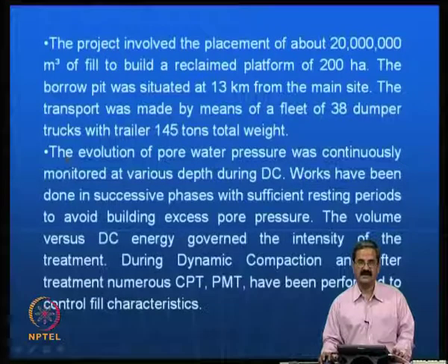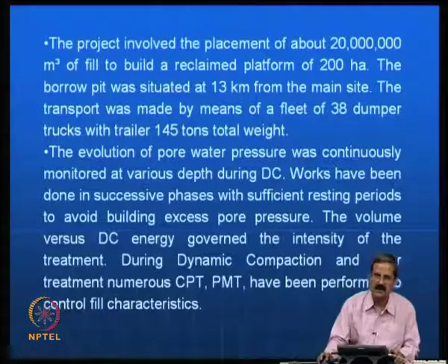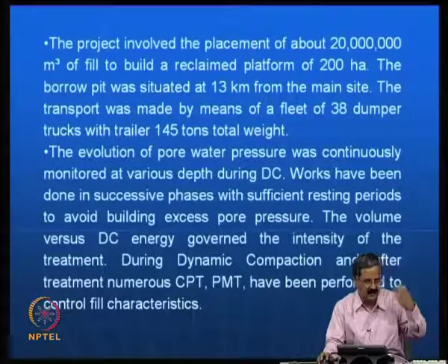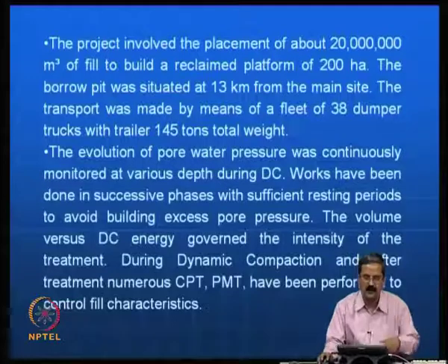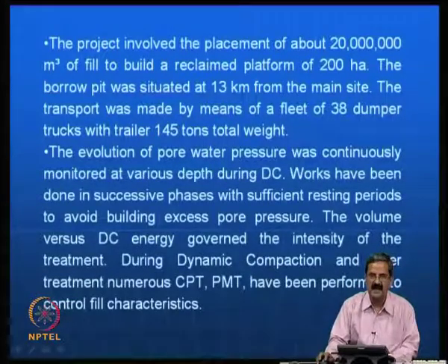So in this case, the pore pressure was continuously monitored at various depths during the dynamic compaction. As I just mentioned, the pore pressure variations during dynamic compaction have a very significant role in deciding about the construction, the tamping operations, the release of load and all that. So the work in this case was done in phases with sufficient resting periods to avoid building up of excess pore pressure. The volume versus DC, or the dynamic compaction energy, governed the intensity of the treatment.